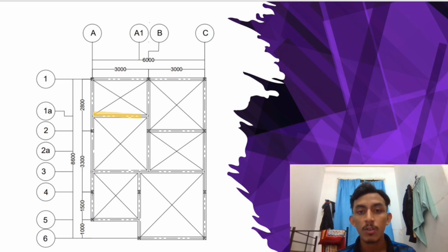After calculation was carried out, design action at the beam is 33.36 kN and the maximum bending moment is 37.42 kN meter. Next, the area of tension reinforcement for this beam is 360 mm² and we use 5H10, for which the area provided is 393 mm².